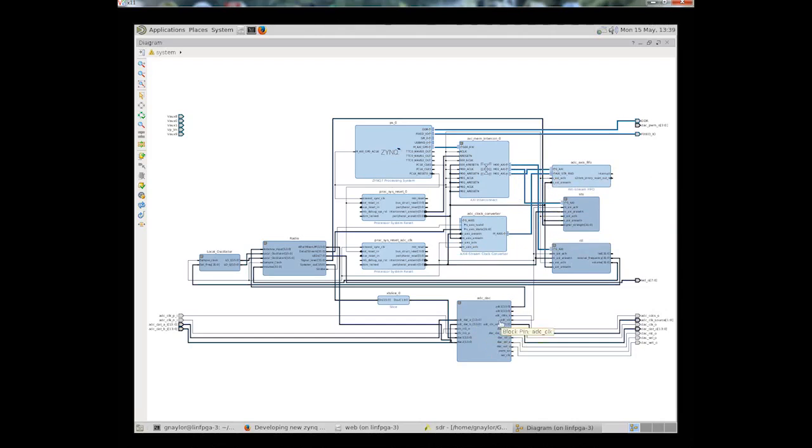So this block here is the ADC DAC interface, which allows us to receive data from the ADC, so in our case from the antenna feeding into the radio block, and then in demodulating that signal in the radio, we put an AM signal back onto this DAC line here, DAC1, and we've also added another signal into DAC2, which gives us some debugging capability.